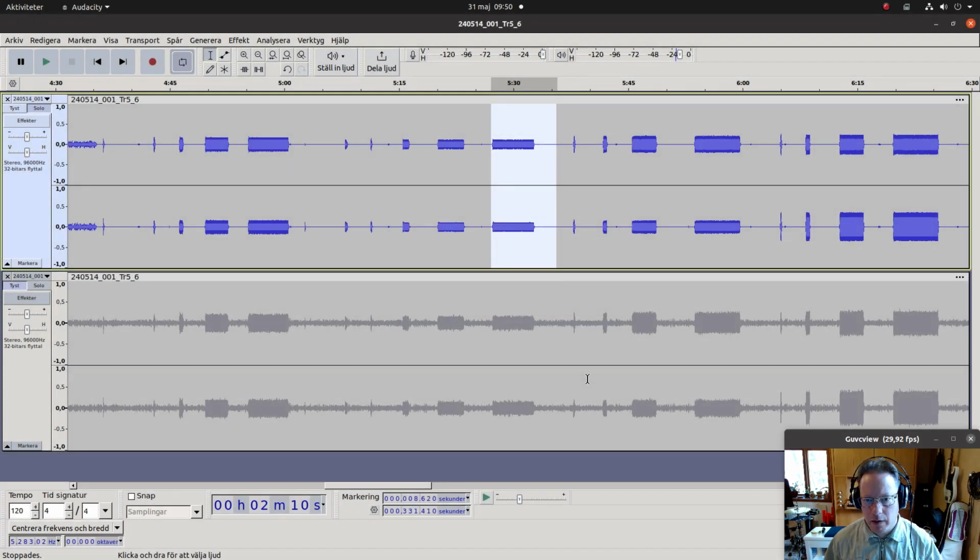You can see that the noise gate removes the softer parts. This might be problematic if the church would have lots of reverb, then you would need to be very careful with the noise gate to not lose it. But well, in this case it works pretty good.